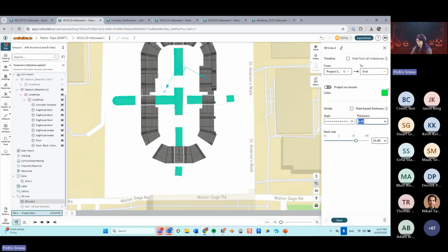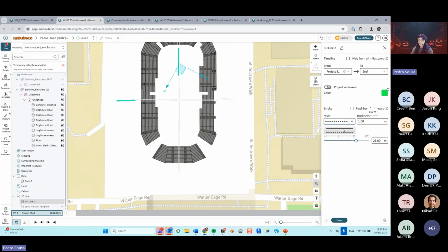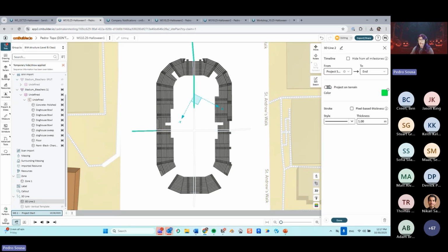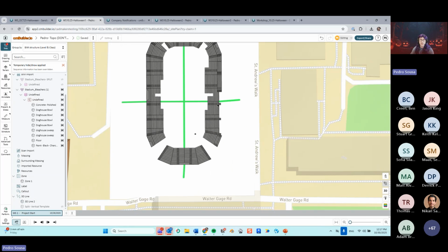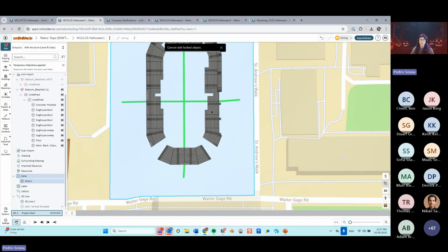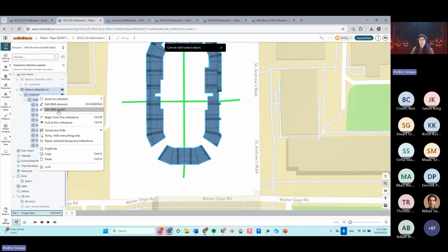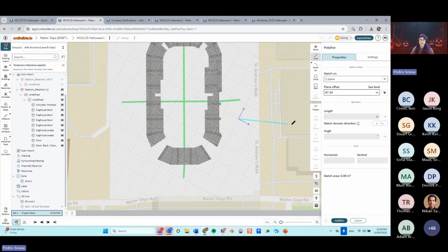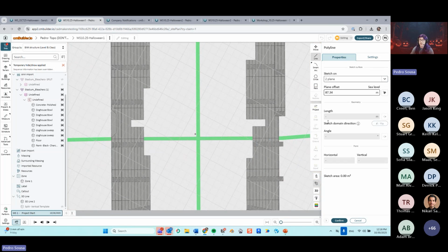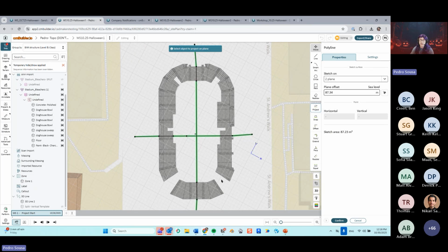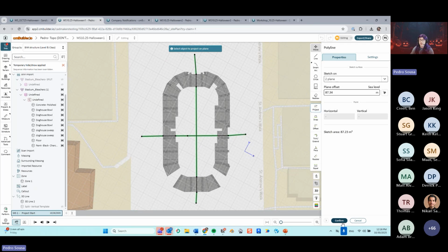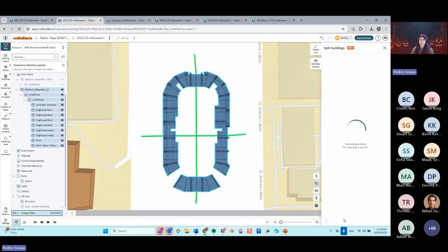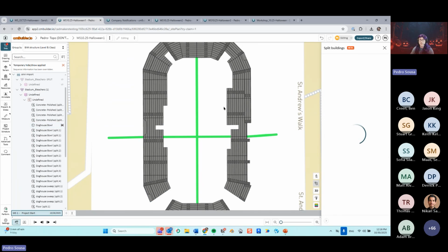Okay. If I confirm now and do this line over here, project this in the ground, and I will go into the split for my model. I will create a line, and I'm gonna do my Z-plane. Now to use this line as my template, I'm gonna go into project and select that line, and that line will be created like that. If I hit confirm and I do the split just like that, and confirm, this split will not create the